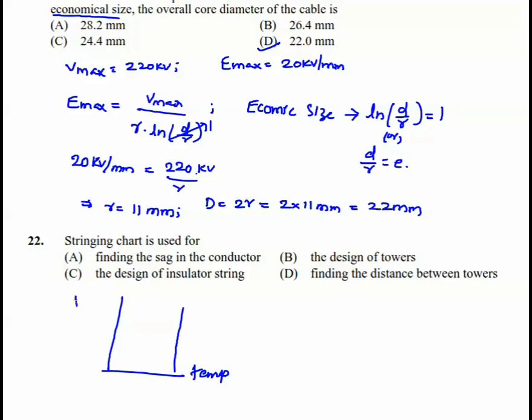This is the tension curve, and this is the sag curve. As the temperature increases, sag will increase and tension will decrease.